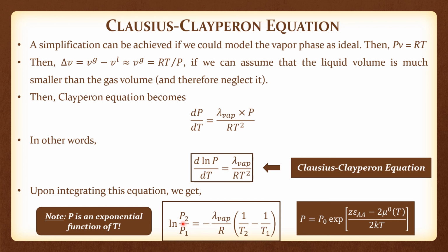So essentially this tells us something of the form that log P vaporization is some A by T, plus some constant if there is a reference state that you want to consider. And such an expression is what is typically used to fit vapor pressure and temperature data. The empirical expression that is often used is called Antoine's equation. So A minus B by T plus C or something like that is what is used. So the A probably comes from here, and the minus B by T plus C comes from this term, so to speak.